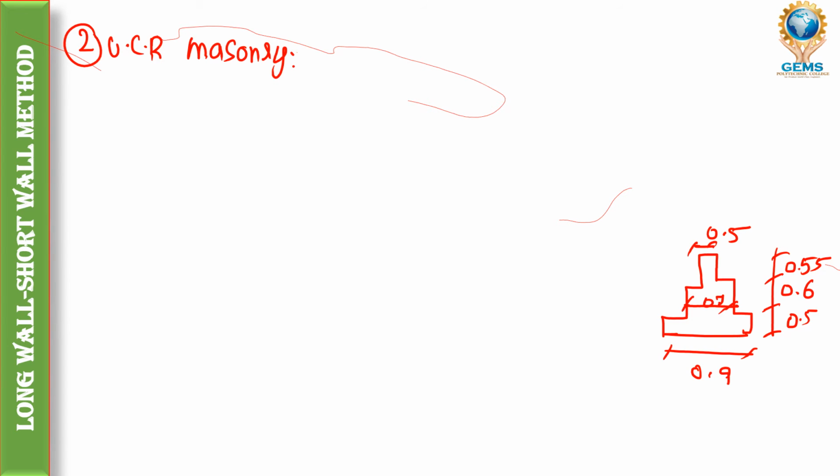Okay, for first footing, second footing, and third footing, we are just going to find for the first step, second step, third step. So for the first footing, we are going to find for the long wall and short wall. So for L1, L equal to L1 plus the breadth. The same procedure for everything. So L1 plus breadth 0.9. So what will we get?